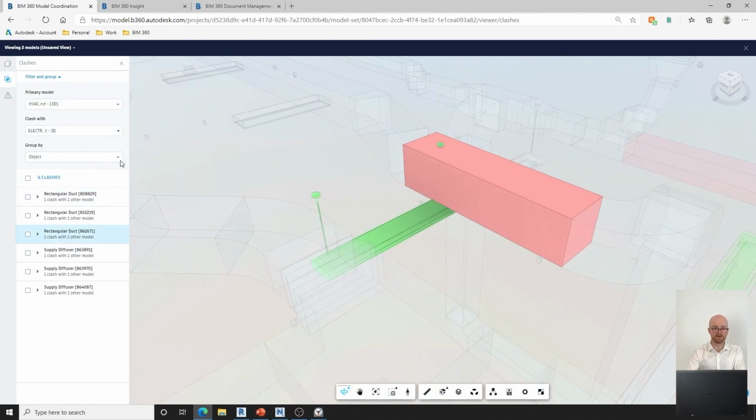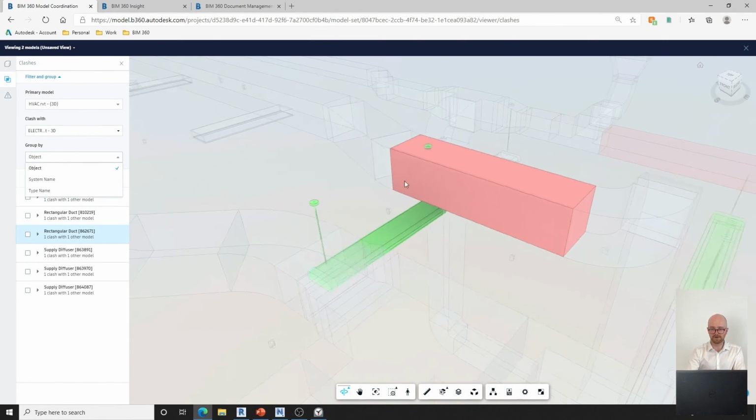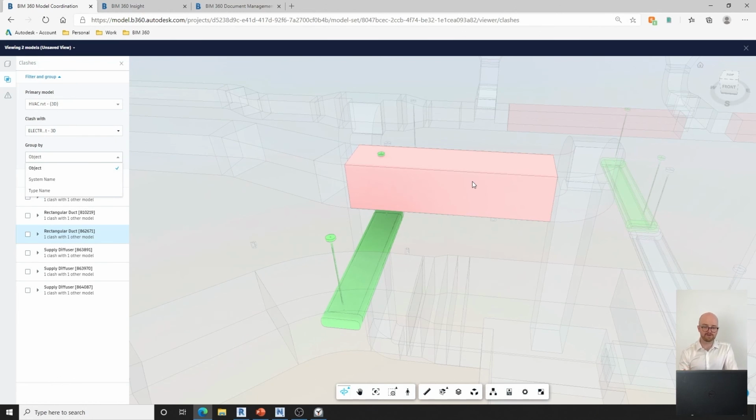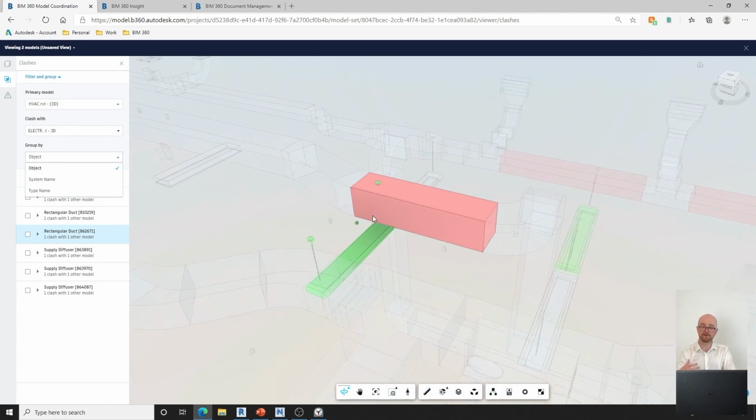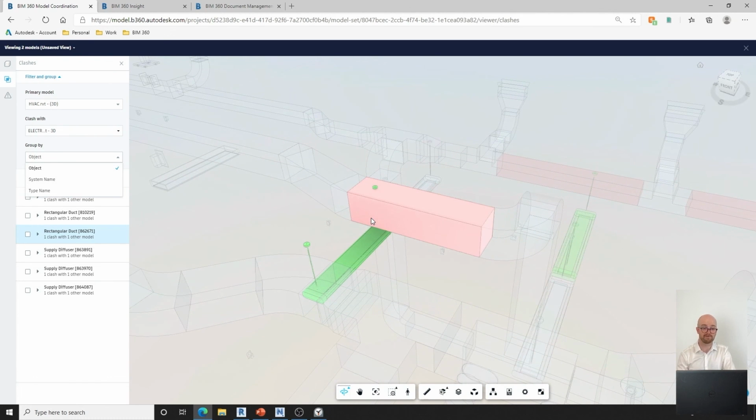And there's various ways that you can filter the type or the way that you look at these different clashes. But this is only going to show me hard clashes. And this is really useful for getting those early design changes in quick to make sure that there are no coordination issues. But what we really need is to also do soft clashes, and use the likes of Navisworks to clash these things. So with BIM 360 Coordinate, you also get a license of Navisworks.